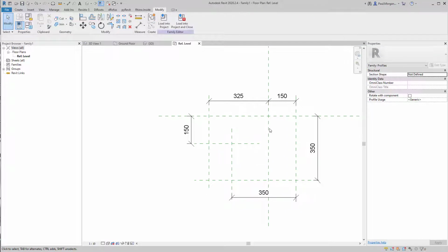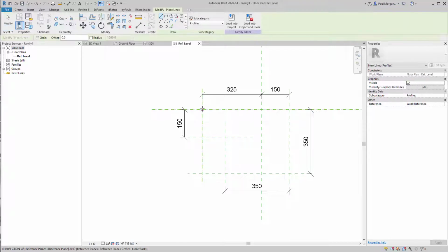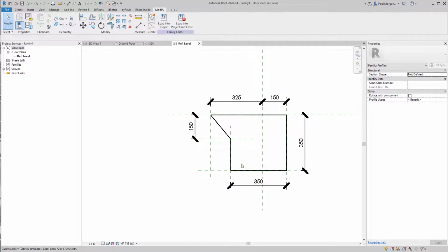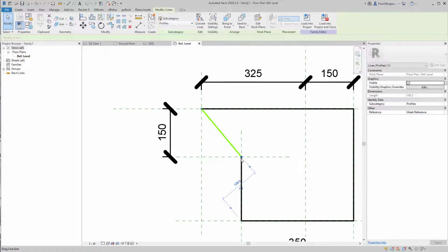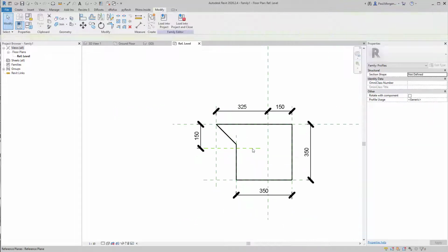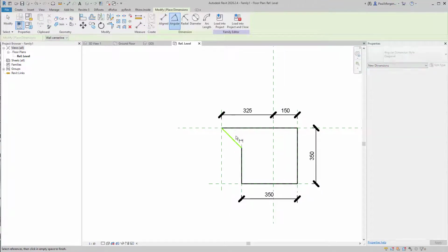Okay, perfect. Alright, so what I'll do now is just grab my pen. So I'll go Create, Line, and I just start drawing. I'm just going to start tracing over this. And it'll look something like that. That's all it is, just a two-dimensional line, like so. That should probably be smaller actually. It should be 125. That should be 45 degrees, which I think it is now. So I can get rid of that. I'll just double check that that is 45. Yep. Excellent.